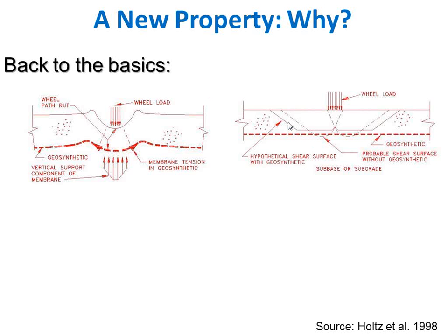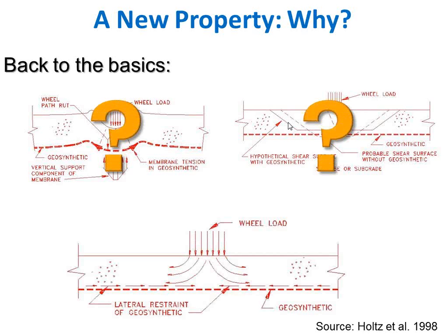It turns out that if we are dealing with a paved road, by the time that we mobilize the deformations that are needed to really come up with meaningful membrane forces, or even to mobilize the bearing capacity, the pavement has been long gone. So there is consensus among researchers, and I would be very curious of the researchers that are in here, I'm pretty sure that you agree, that the mechanism that really makes this system work is a third one, which has been defined as being lateral restraint.